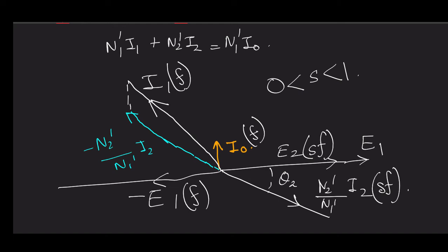When you are considering S less than 1, it implies your rotor structure is rotating at subsynchronous speed, but its speed is not 0. Rotor structure speed is 0 only when S is equal to 1. Otherwise, the rotor is having some value.